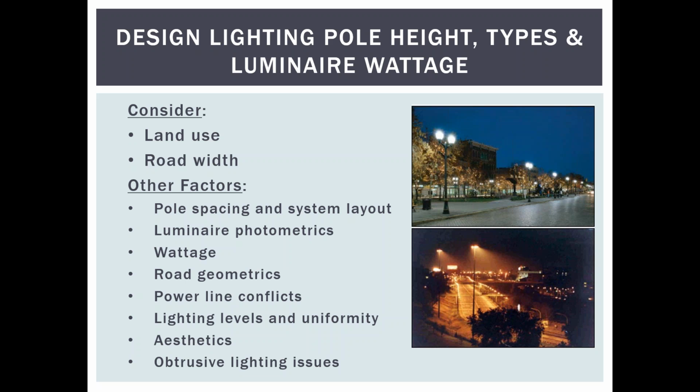In residential areas, the designer should also select pole heights and fixture wattages to reduce spill light into those that are suitable for residential areas or to nearby homes. And many times we have had to use shields to protect nearby homes from light spill. Determination of pole height and luminaire wattage is made using computer lighting design software to test different scenarios by a trial and adjustment process. Today's computer lighting software allows a designer to undertake calculations in minutes, thus allowing the designer to explore many more options than were practical in the past.